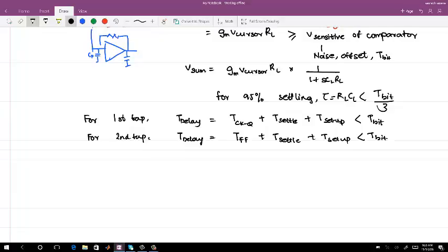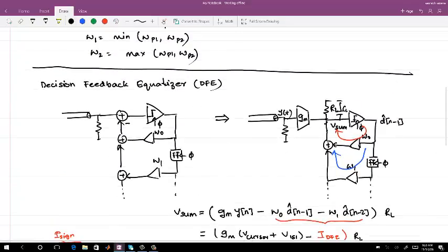So you see here, right? Dn minus 1 basically transfers to Dn minus 2 at the second. You are creating a finite delay element, a finite delay between the first and the second bit, right? So you need to clock it. It means that if you do not clock it, then you have to have some kind of delay element which is tweaked to exactly 1 unit of delay, right?